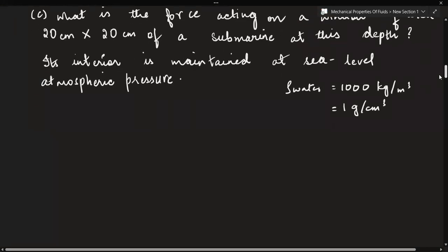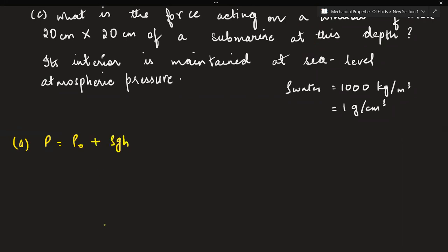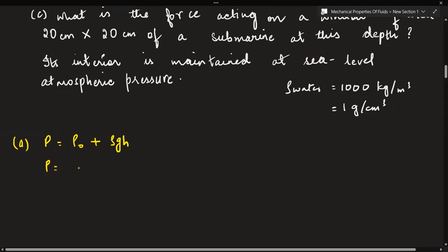But for the absolute pressure, the first part, absolute pressure is equal to atmospheric pressure plus rho g h. So, what is the atmospheric pressure you've taken? You have multiplied atmospheric pressure with gauge pressure. That's how your 10 to the power 12 is coming. See, atmospheric pressure is 1.01 into 10 to the power 5 or 1.03 into 10 to the power 5, plus rho g h.